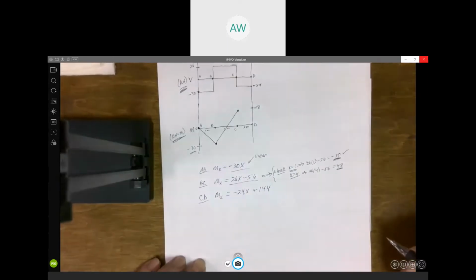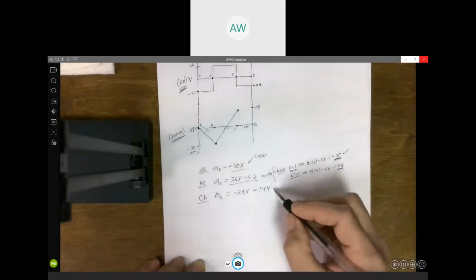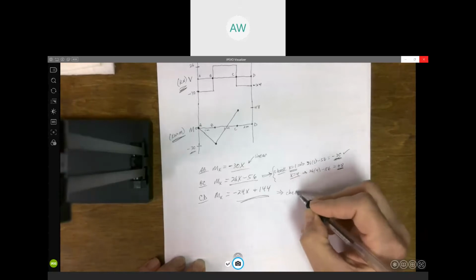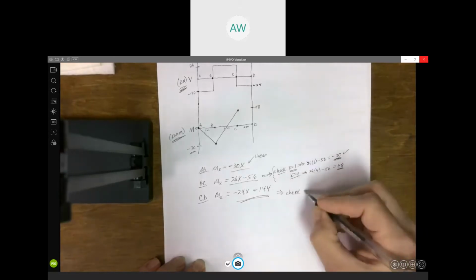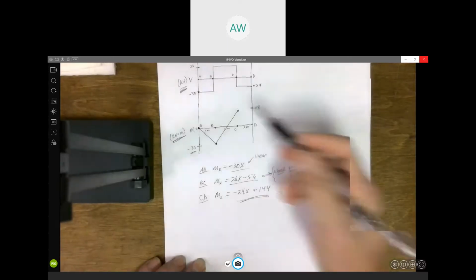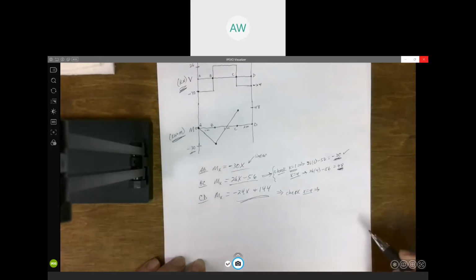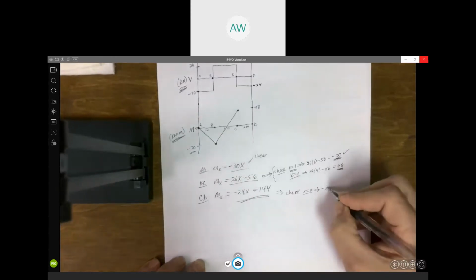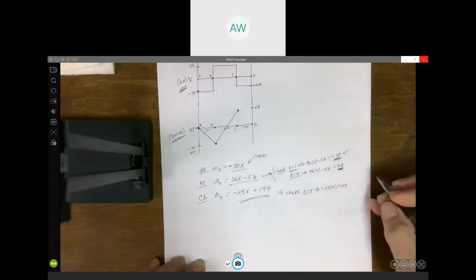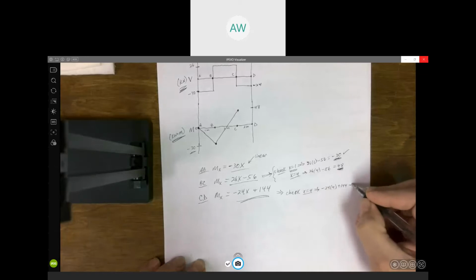That's pretty straight. So any question about that part of the moment diagram? All right, so we're almost there. We just have to do this last one. Again, check. When x is 4, we should get the same thing that we got where that one ended. We should get 48. And if you do minus 24 times 4 plus 144, better get 48.